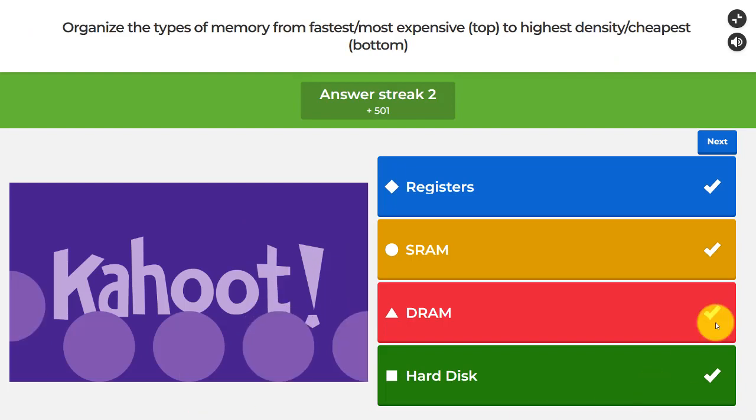And coming back to our puzzle, indeed, the top one is the registers. Those are the fastest and the most expensive. Then SRAM is the embedded memory. It's the next level down. DRAM is already going off chip, so that makes it a lot slower, but we can make very cheap bit cells. And going much farther, and this can take even millions of cycles just to access it, we get to the hard disk, which is really cheap, but it's also very slow.